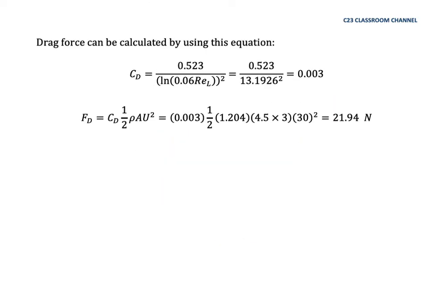So drag force can be calculated by using this equation. First, we calculate the value of CD. So from the data, it is equal to 0.003. And then we use the common equation for drag force. And then we could get 21.94 Newton.